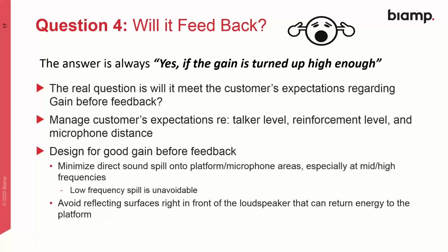Avoid reflecting surfaces right in front of the loudspeakers that can return energy to the platform. That picture I showed of the loudspeaker in front of the stained glass window, there was a reflecting surface above the speaker that returned energy to the microphones.